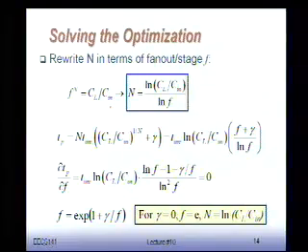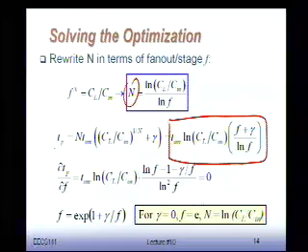We can take the log of that, and you can find n as a function of ln f. So we can write down our propagation delay, and we have this expression where propagation delay is basically only a function of small f. That's the only parameter I have. I have to determine what small f is going to minimize the overall propagation delay.